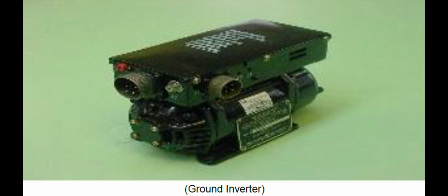Inverter transfer relay. The inverter transfer relays are located on the left attic compartment shelf. The relays, one for number 1 primary AC bus and one for number 2 primary AC bus, are 4-pole double-throw contactor relays. The relays transfer 3-phase inverter bus loads from the primary AC buses to the ground inverter when the inverter is the only source of power available.